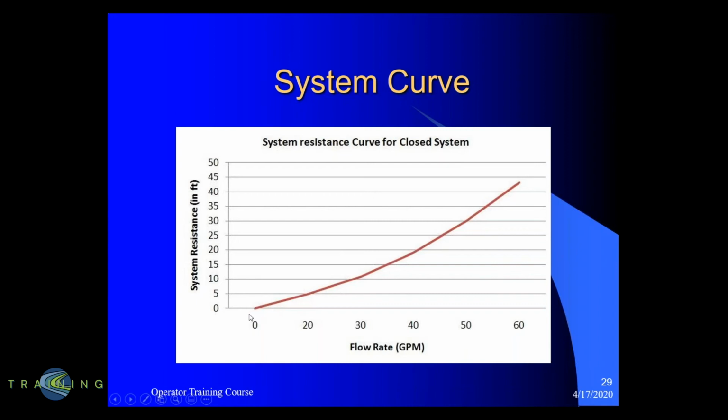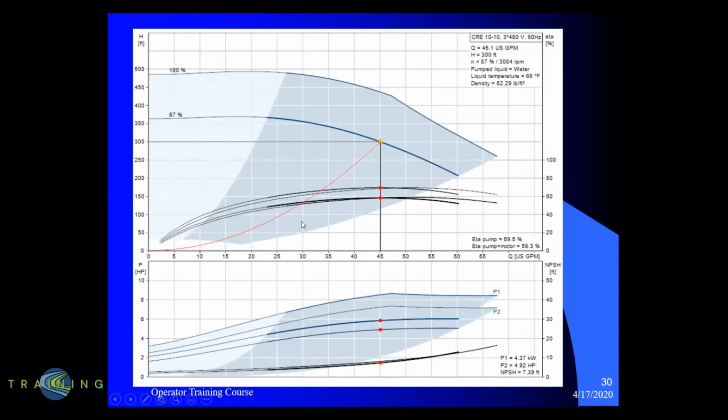But as we are doing design, we start plotting flow through that system. Then we add our static head, and we end up with a pressure curve, a curve that looks like this red line on our performance curve. This will be our system pressure curve.